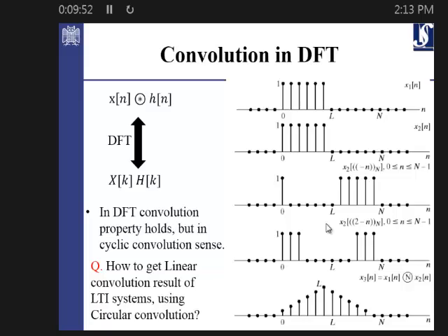And that window is actually the size of the signal that we have. For example, here if you assign the signal to be the size of N, starting from 0 to N minus 1, which means the signal is of size N, then convolving these two signals means that first of all you have to reverse the signal in time. One of them should be reversed. For example, x2 of n should be reversed. You can assume that it's a filter. But reversing it means that you need to do everything in reverse in a window of size N.